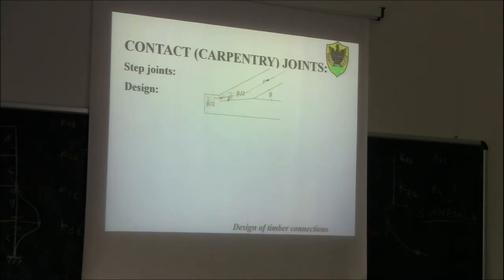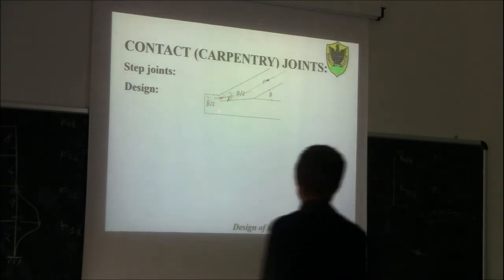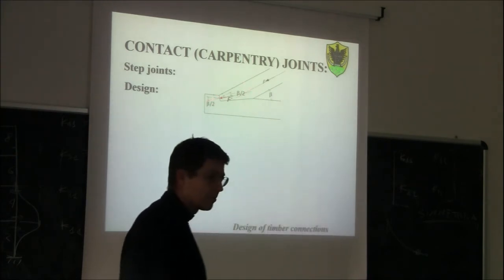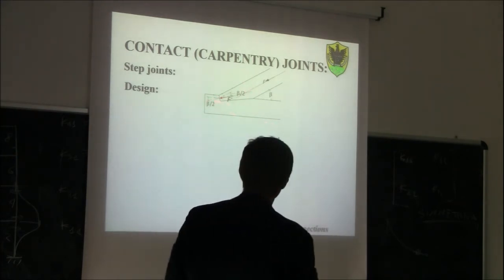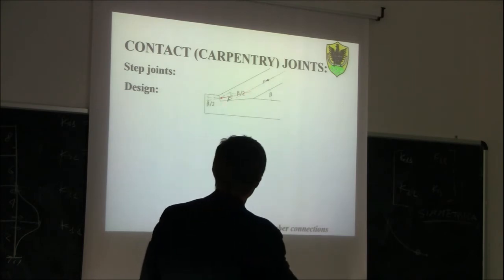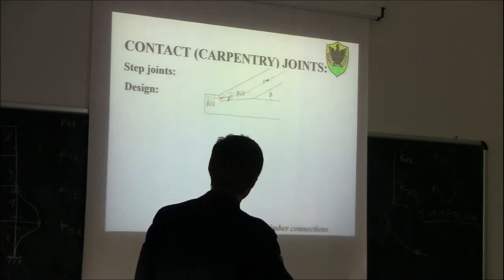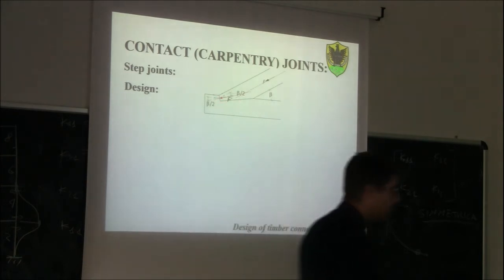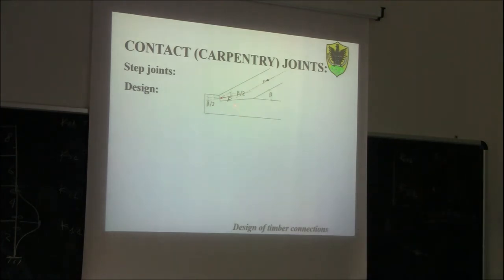So, how can we solve this problem? We know the direction of the force of the rafter, which is basically the axis of the rafter. We also know the direction of the other two. But if we assume that both other directions go through the middle points of those carvings, we wouldn't get to the same point. If you take the other direction through the middle point, then they wouldn't join the other two lines at the same point.